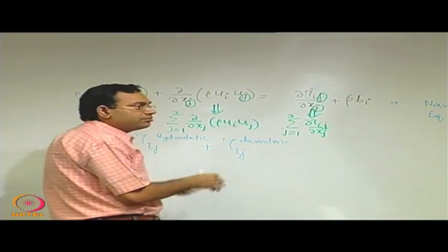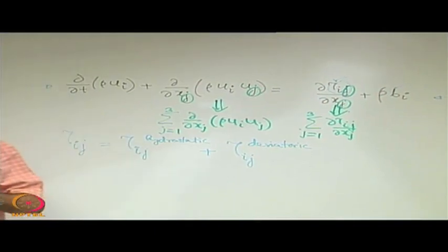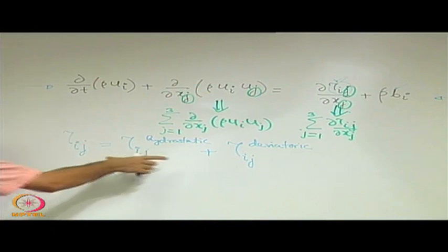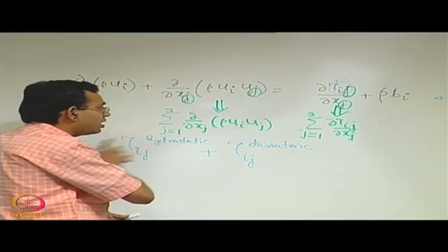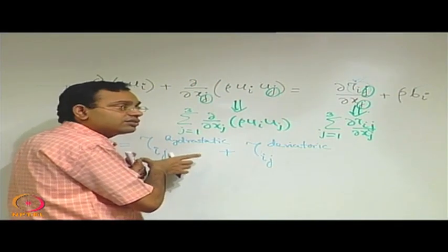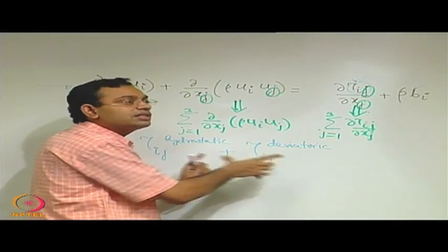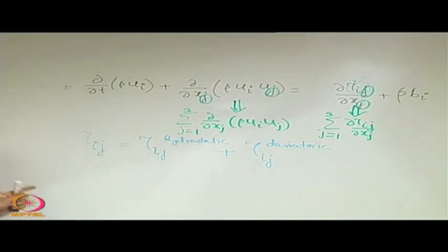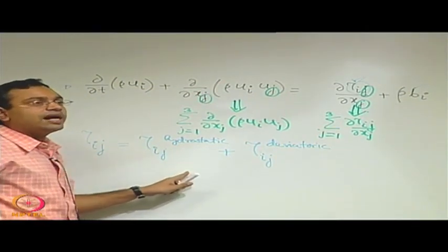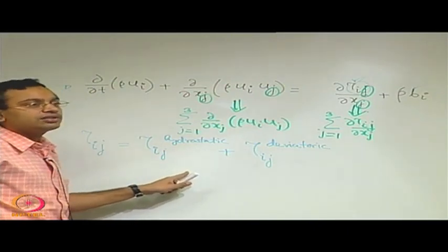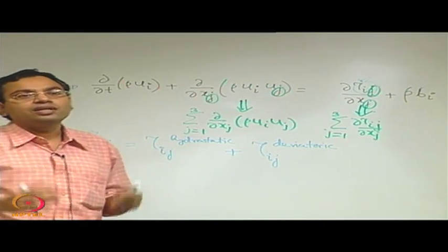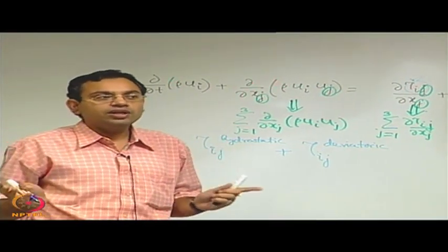Hydrostatic component, from the name, is clear that it talks about a static condition, so it is not related to deformation. So, we can broadly say that we are decomposing it into two components. One component is not related to deformation, another component is related to deformation. That is the whole idea. And the component that is not related to deformation should be only a function of pressure, because when a fluid is at rest, you can only have the description of the equilibrium through the pressure.